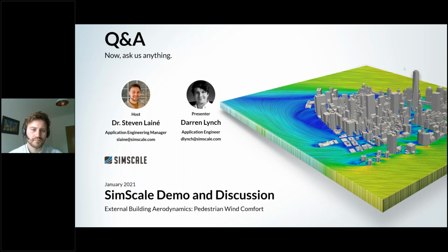We then use best practices to do a conversion from that to the weather data. So the weather data might say for, I don't know, 5% of the time in a year, we might have a wind direction from the northwest at 5.6 meters per second. Then we would scale those results to that wind condition. That's essentially what it's doing in the background, and that's how we calculate the pedestrian wind comfort map. What you see in the velocity results will therefore be the reference results, which is at 10 meters per second. Okay, please let us know if that didn't answer your question, and we can follow up.